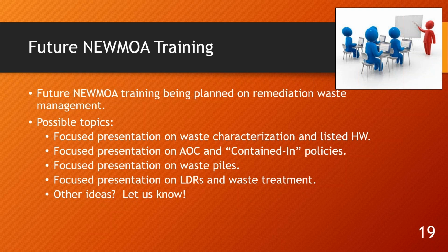I think the biggest rule of thumb is don't remove it from the area of contamination until you've actually made a determination that it is not a hazardous waste. So bear in mind that as soon as you generate the waste, you are required to make a determination. Now, if you're doing a test pit, digging it up, testing it, putting it right back in, most states, I think all of them, consider that you haven't generated it at that point.